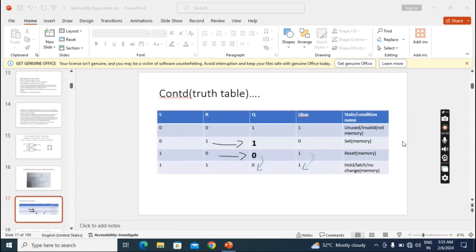In this lecture we'll discuss the order of input combinations that we apply to non-gated latches. For example, I take a non-gated SR NAND latch. It contains 2 inputs, so we get 4 possible input combinations: 0 0, 0 1, 1 0, 1 1. You may have a doubt: do I need to start from 0 0? Can I apply 1 1? Or can I apply some other combination like 0 1 or 1 0?